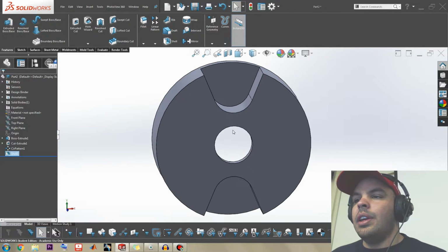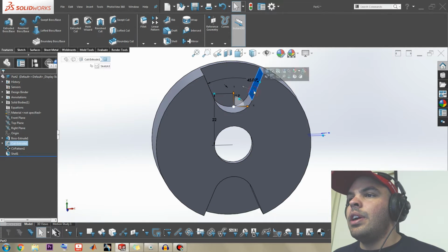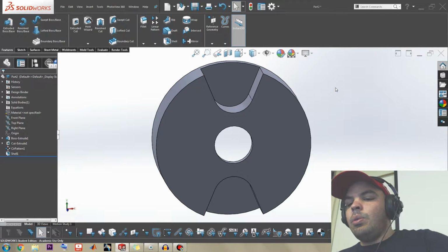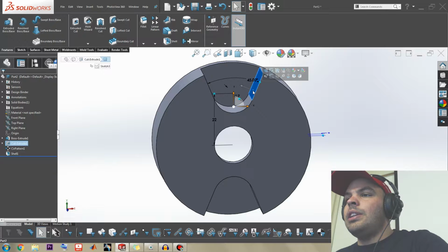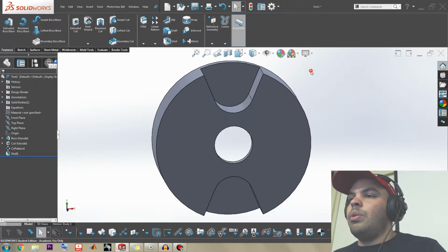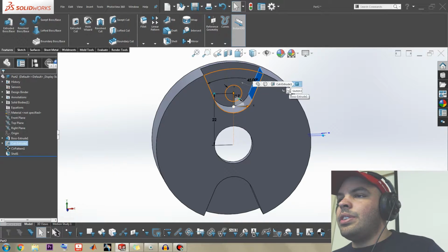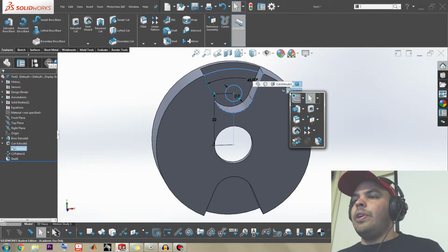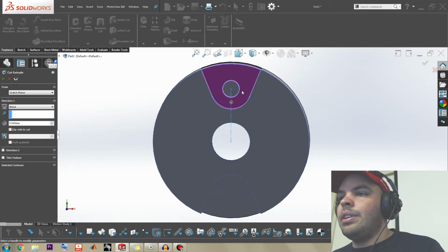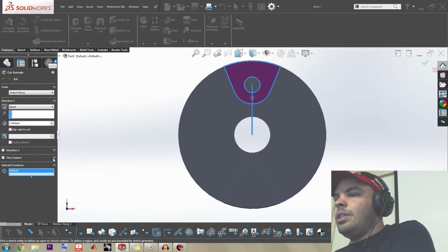Looks pretty cool, right? And then what we can do is, he uses breadcrumbs, but another thing is he gets the breadcrumbs right to his cursor, and the way you do that is you click and hit D, which brings it straight to the cursor. So click D, sketch, and then you can combo it right into the S shortcut, extrude, but we just want not one contour, so it needs to get out.